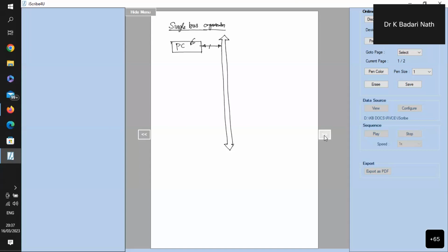Now, there are two registers we have studied which are important to establish an interface to the memory. One is the memory address register, the MAR, and the other is the MDR, the memory data register. The MAR has one input and one output. That means you can write into the memory address register either from the program counter or from other registers, and its contents can be output to the memory bus, the external bus. So it is one input, one output.